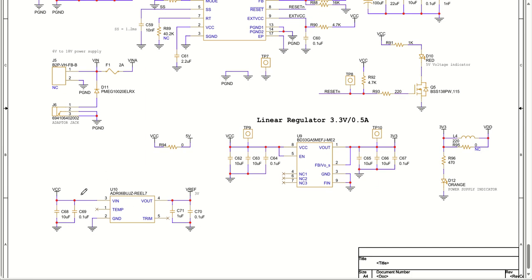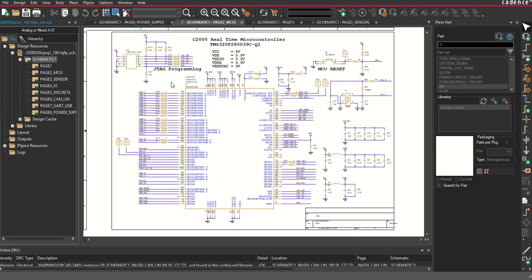Similar to that, we have a voltage output for V reference. So 5 volt is getting converted to 3 volt voltage reference that can be used for your ADC and DAC. Now let us get into the circuit design that we have done through OrCAD. So this is the particular circuit that you saw just now.